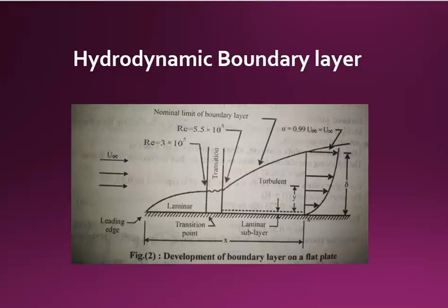The pattern of flow in the boundary layer is judged by the Reynolds number, where x is the distance along the plate measured from its leading edge. The transition from laminar to turbulent pattern of flow occurs at a value of Reynolds number between 3 × 10^5 and 5 × 10^5. Besides, the critical Reynolds number, the coordinate at which the laminar layer begins and stabilized turbulent flow sets in, depends on surface roughness, plate curvature, the pressure gradient, and the intensity of turbulence of the free stream flow.